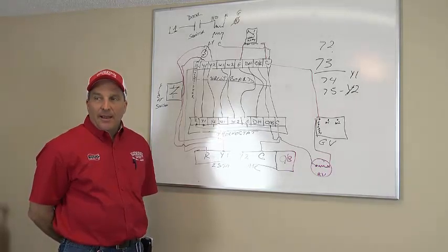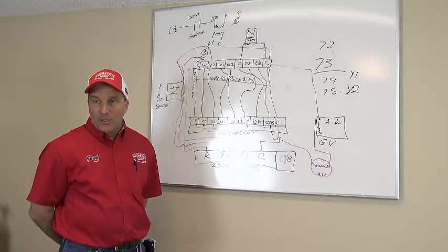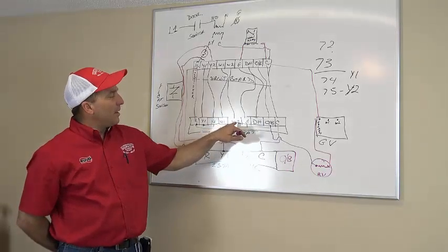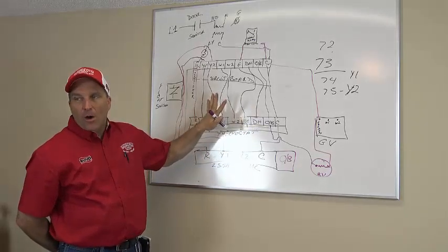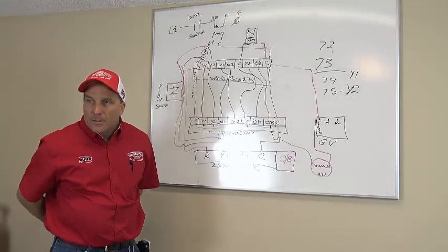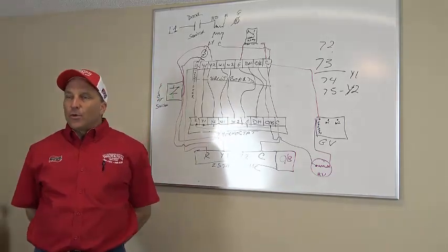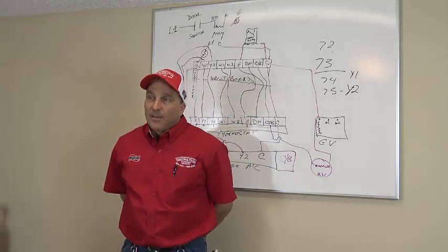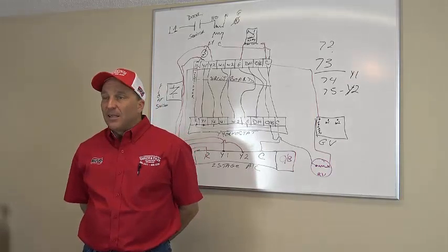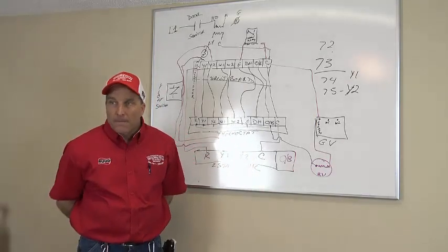And let's say I have what's called the dual fuel system here. I'm going to call this one the dual fuel system because I'm going to call my W1 and my W2 a gas furnace for this sake here, okay? So far I've energized O and B because this is dual fuel, and dual fuel means that I have a heat pump for first stage heat and I have gas heat for second stage heat. Okay? So it's going to hit first stage, so it'll be W1.